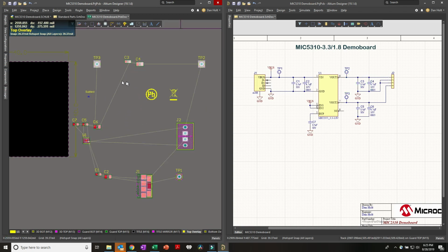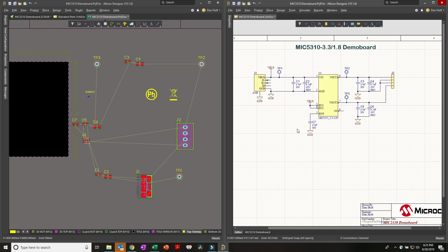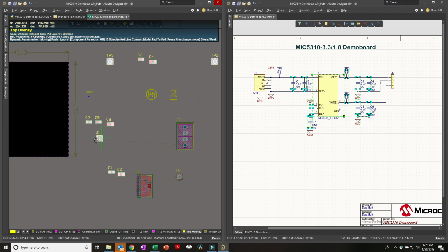So now, even though they can be all interspersed, and this could be 50 parts, I can grab this whole block out of, let's say, a much bigger schematic and drag this whole block off to the side, do a little mini layout of the parts, and then drag it back into my PCB. So you can see how powerful this is. So even if I just take, let's say, the IC and the bypass caps that go around it, that represents this block, or this grouping here.